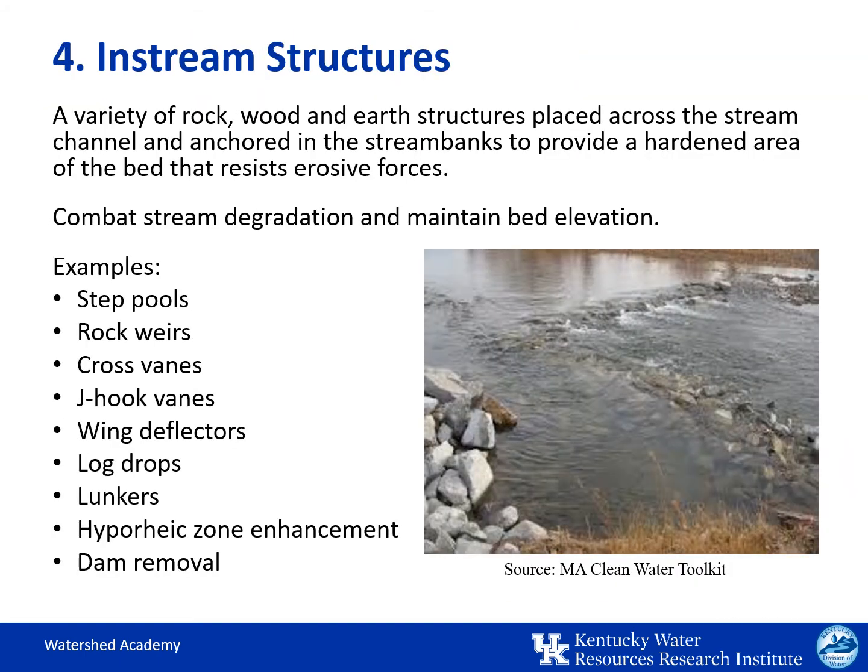Having addressed some of the techniques for bank stabilization, we come to our final piece in this presentation, which looks at the in-stream structures to address the profile and cross-section of the stream channel. Land uses involving the installation of culverts, straightening of channels, and removal of riparian vegetation can all cause damaging changes